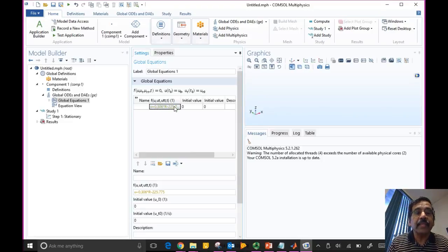Okay. Now it gives me unknown variable because I haven't declared what the variables are. When I enter an equation, I can introduce a lot of symbols. I have to tell Comsol which is the symbol that I'm solving for. You can obviously have more than one symbol. So I need to identify in each equation at least one symbol that corresponds to that so that it labels them as the unknown. So here I can say x is my unknown. Okay? But still it's going to give you the warning.